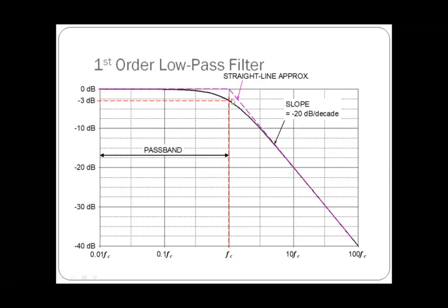We can see here at this point it has coincided with my characteristics curve, which is shown in the black line. So where it coincides, from there I am going to draw a vertical line. So that vertical line is going to coincide with the frequency axis, on x-axis. So that frequency we are going to take it as the cutoff frequency of a low pass filter.